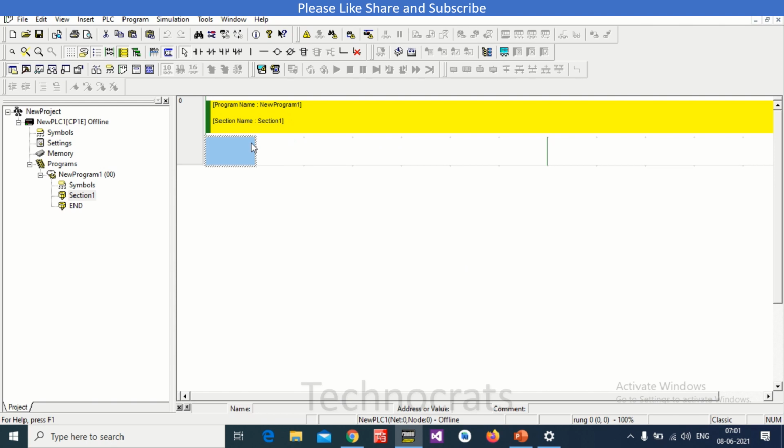So I will write P_First_Cycle. Initially we will initialize all the data registers like D1306, D1307 and your Modbus polling bit, that is A641.0, and .01 is for your feedback. So we will reset A641 whole data area.